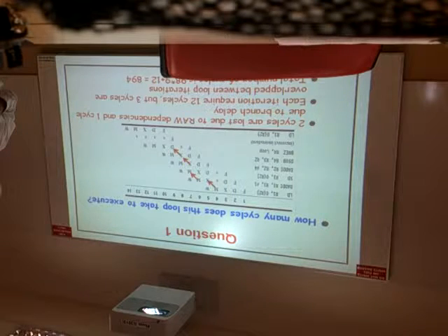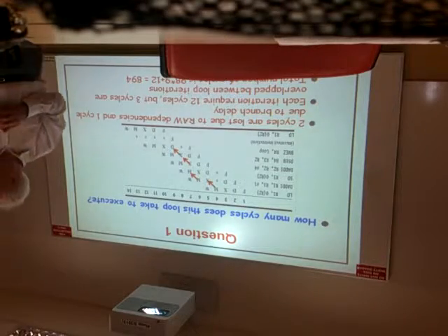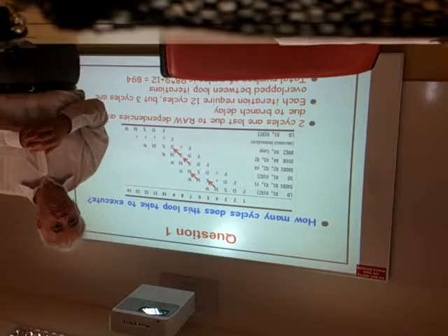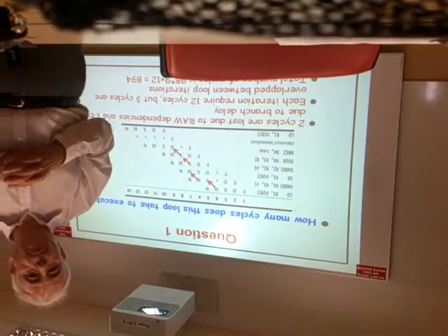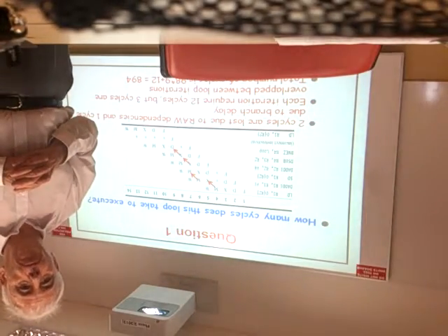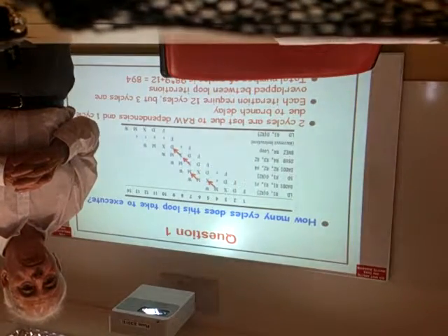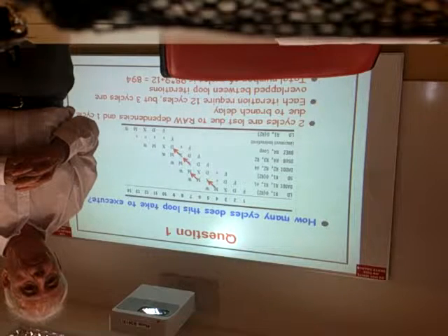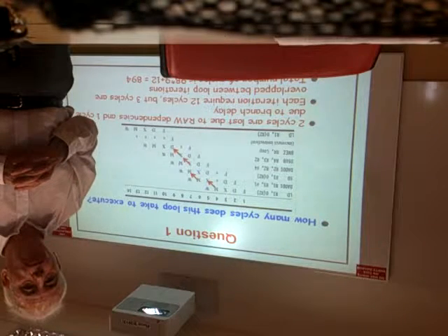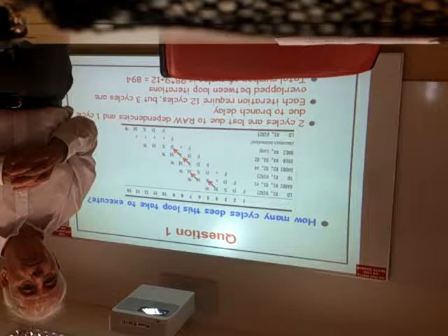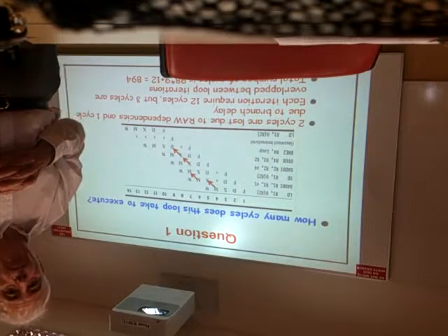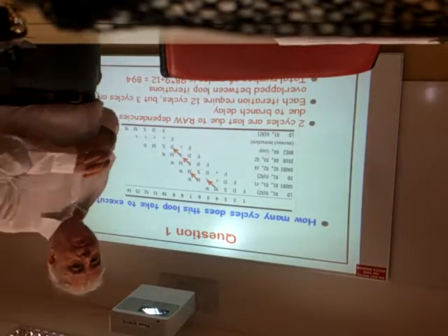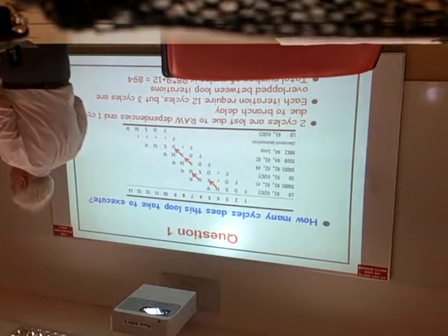But you see instruction 2 and 3, right? The store one is after the F, but the second line is after the D. Because the third line, you need to fetch the thing. During the previous add, you decode. At the same time, one is decoding, one is fetching. It's not doing the same thing, that's why you can continue. Okay, so I think we move on to the next question.